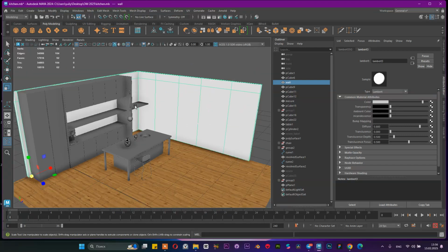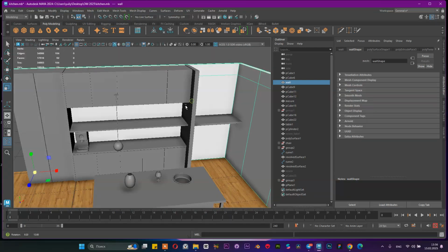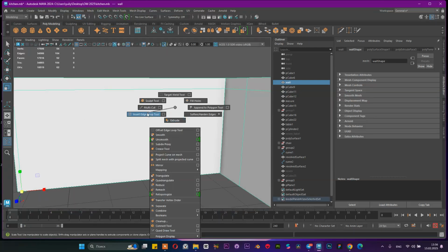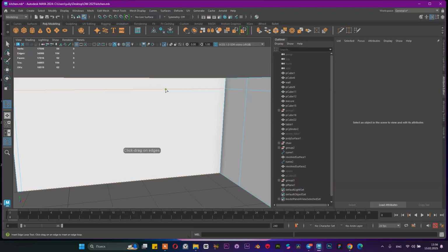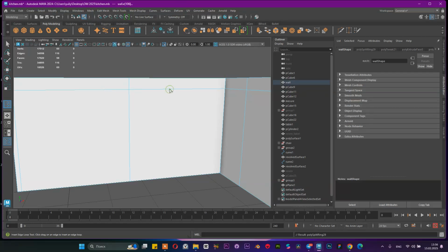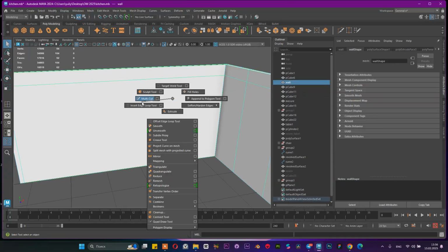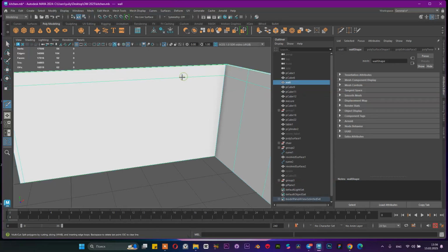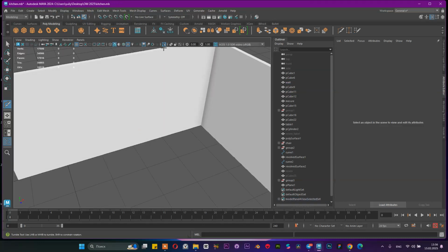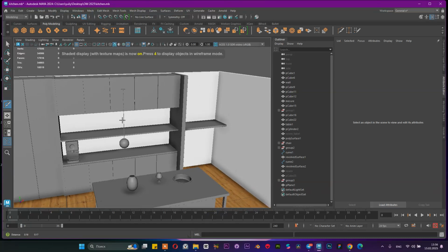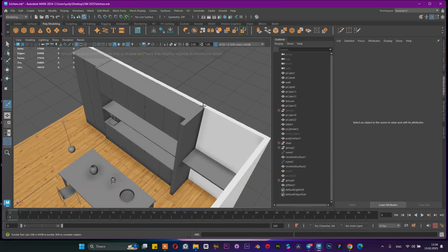walls. And after that, I can focus on the marble, and I can model, for example, with the insert edge loop tool or make some divisions with multicut to divide faces for this. My computer is really slow. Okay, let's divide this model.